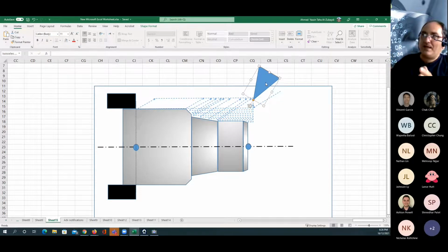The only thing you need to do now is every time you sketch a tool path, you need to find the points that the cutting tool tip is going to be moving between. So we're starting from here, we're going to here, so we need this point. So we can write down the G00 to this position. And G01, you have to put the value for the Z and this position. G00, the X and the Z here. G00, you know this point already.